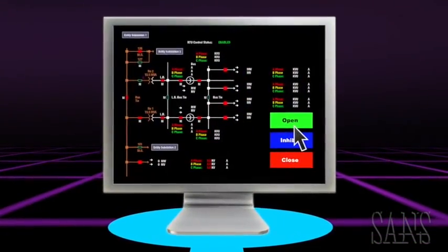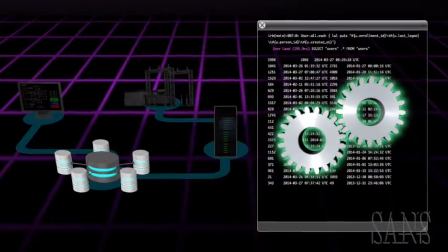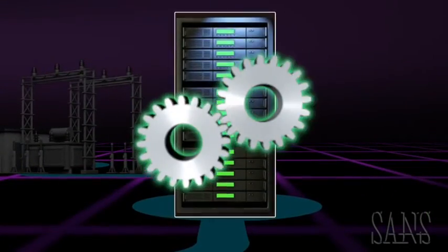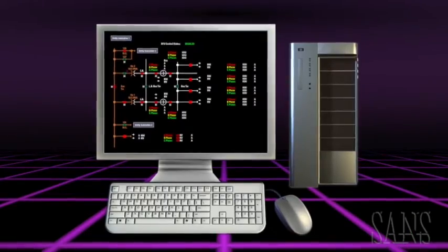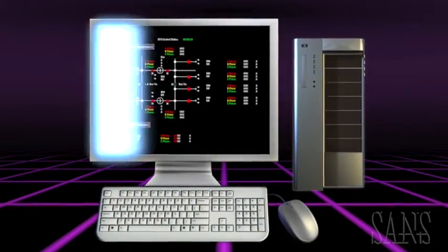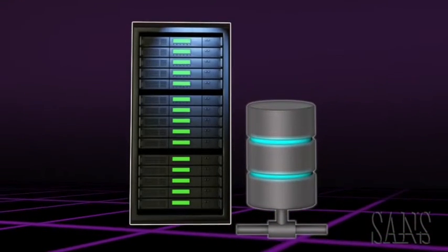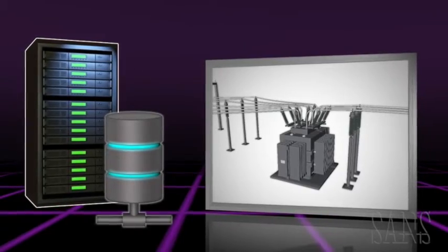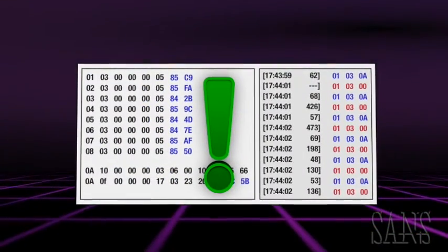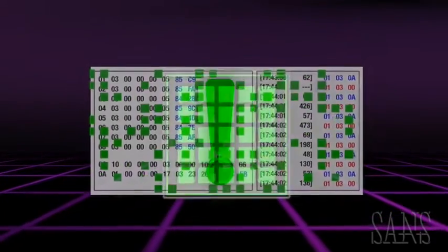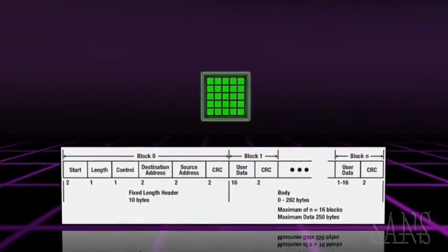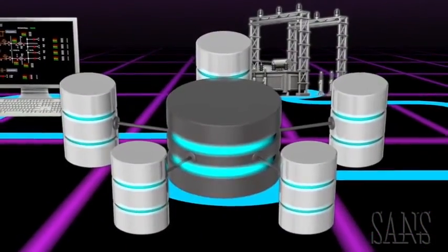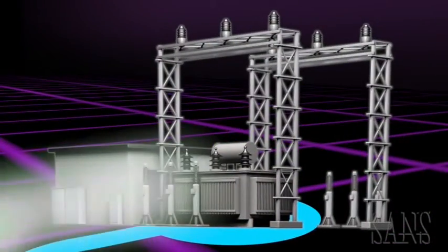For example, when the switch was controlled, a corresponding record was changed in the database. The new state of this record is then sent to the communications front-end servers for processing. At this point, the operator action has moved from the keyboard to the EMS application, then to the communications front-end servers, which will route the performed action to the appropriate field communication lines. In order to deliver the message to the destination, it needs to be formatted into a specific language or protocol that can be routed to the field device. The formatted message will traverse the system by a routing database that will ensure delivery to the correct field location.